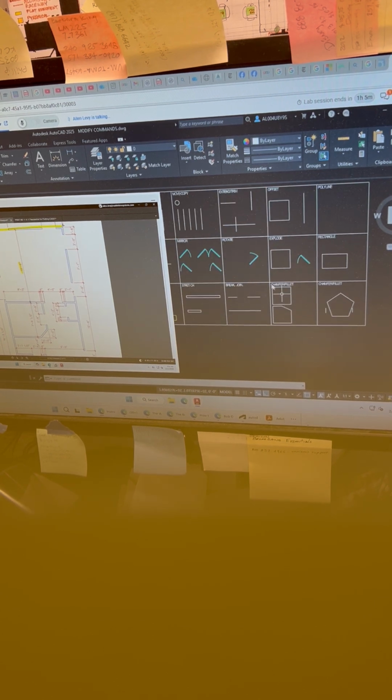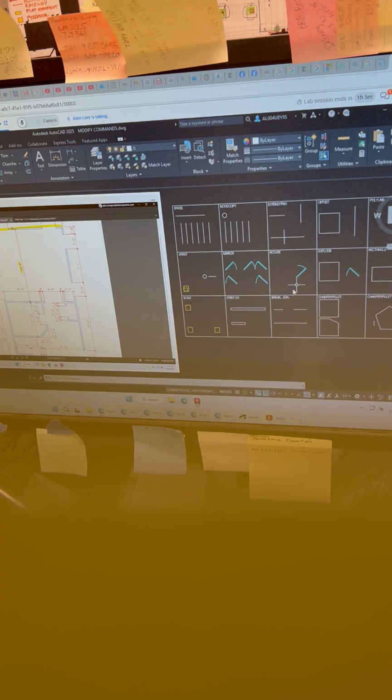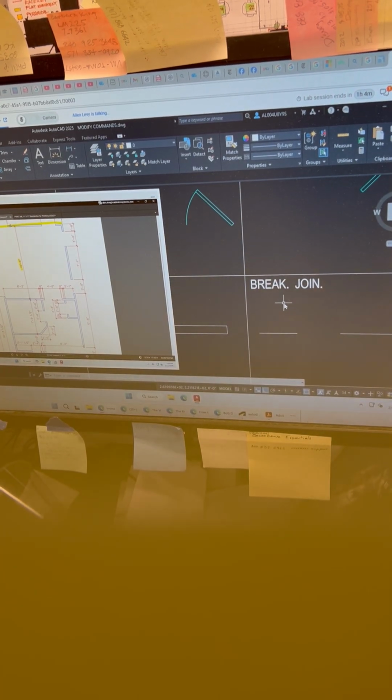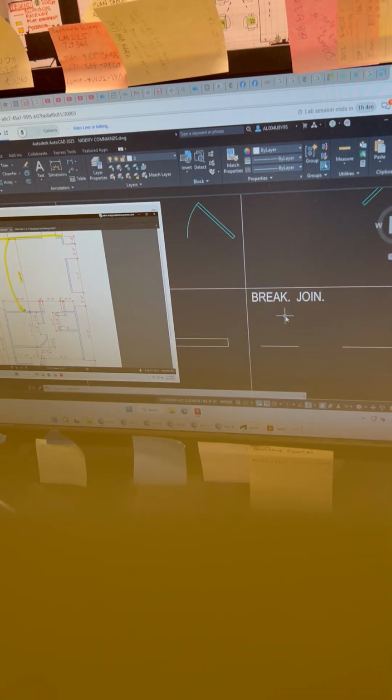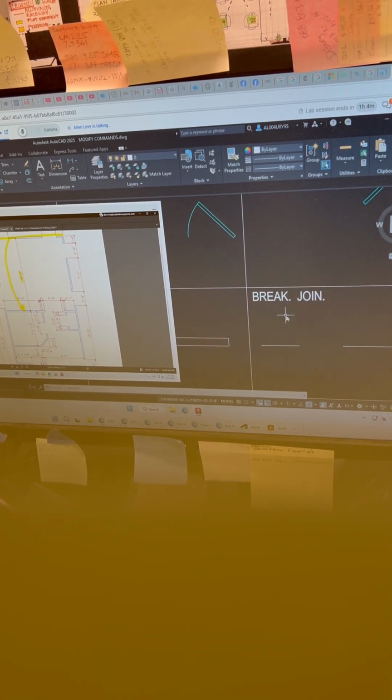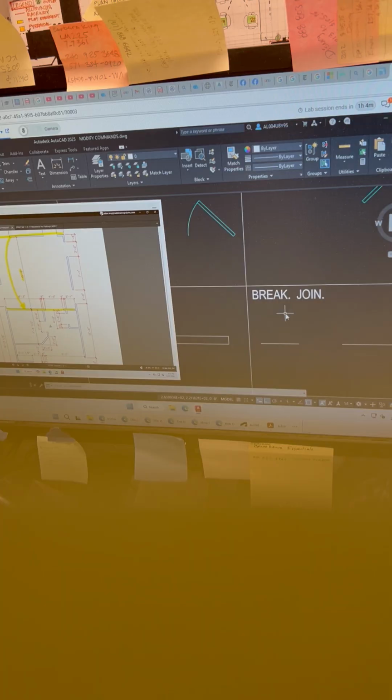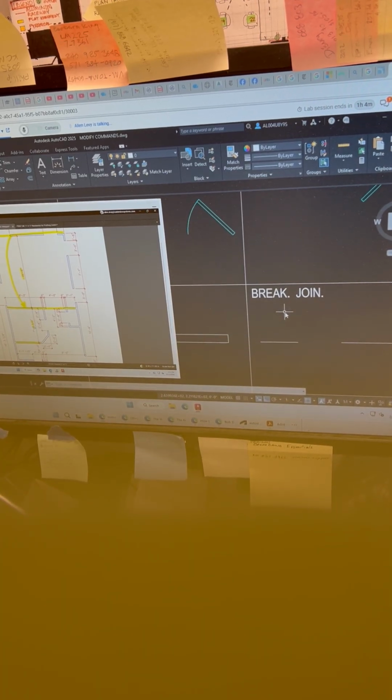Because you're going to have things like dimensions, and you're going to have existing geometry. And basically what you're going to learn from me today and apply this to our exercise tomorrow of this bedroom plan is you're going to be able to locate the other elements using dimensions and offsetting those objects by those distances. And therefore you're going to have other geometry, and everything is going to be located using an offset command.